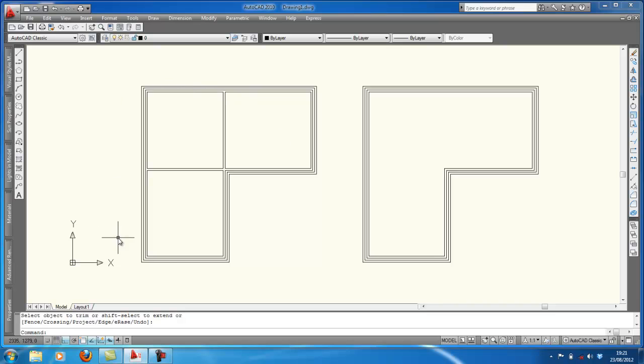Now you have an outline of a masonry in the house. And really, if you were looking at the foundations, and if those were the bearing walls, this is what you will get at a plan of the foundation. So this is below the DPC, especially if you've had suspended timber floor.